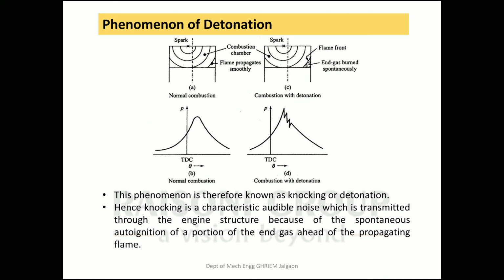It may be noted that knocking in diesel engines is a different phenomenon. Knocking or detonation in a spark ignition engine always occurs near the end of the combustion, whereas in the diesel engine it occurs in the beginning of the combustion.